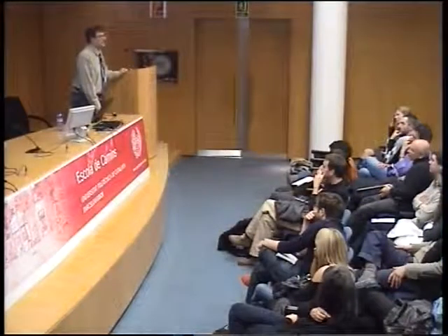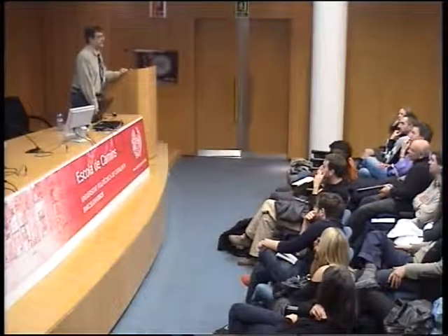The best thing you can do about the encroachment of vegetation is to allow some kind of flood releases on a periodic basis. And again, it's this issue of interaction of vegetation and sediment transport. Rivers adjust so they can fight back against vegetation, which would close the channel. And there is a balance between vegetation encroachment and removal by the power of the flow itself. We take away that power, and now we see a vegetation morphodynamic narrowing of the channels. So restoring at least some of the flood peak is the best way to deal with that.